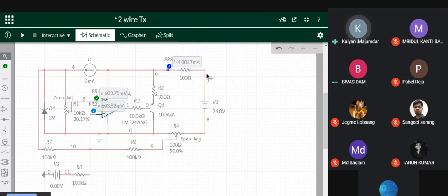The direction is to the right. That means you'll get a negative sign, because actually current is flowing from right to the left, since there's a positive terminal. Its current is flowing in this direction, but this current probe is measuring current in this particular direction, which is highlighted by the arrow. You probably can't see the arrow, it's very small. So all you get is a negative sign, and you can just disregard it. That is not important. What is important is input voltage versus current.